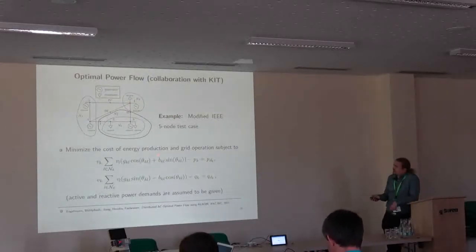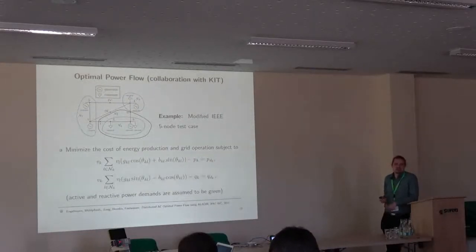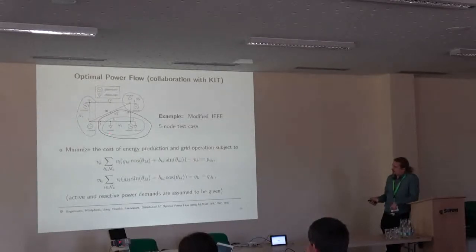But what we see is that these power flow networks are horribly nonlinear, since we have these products of the voltages here, and then there's also a phase angle between the AC currents which has to be taken into account. That's another optimization variable which enters in a very nonlinear way through these power flow equations.